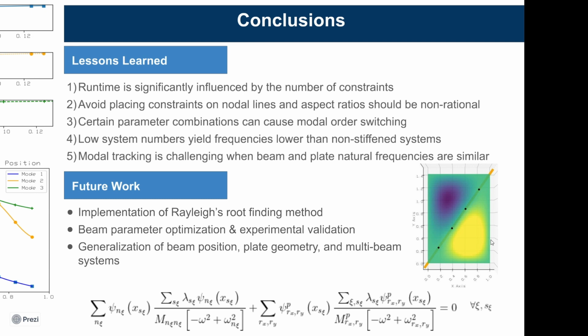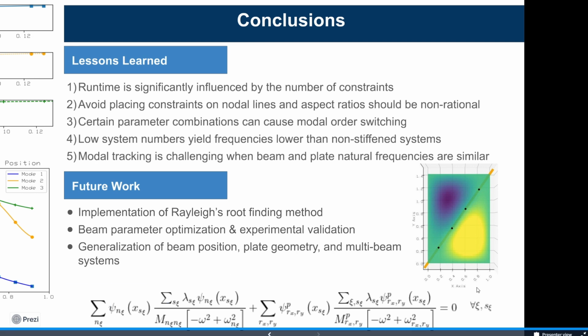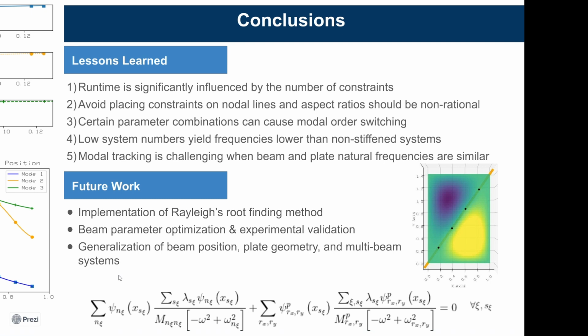Here, I provided the first mode shape of a more general condition of the pinned plate case where the beam is along the diagonal. Also, here is an equation that I have derived for the general case of multiple beams. Finding the roots of this characteristic polynomial posed by the equation will yield the natural frequencies and the mode shapes of any general system.